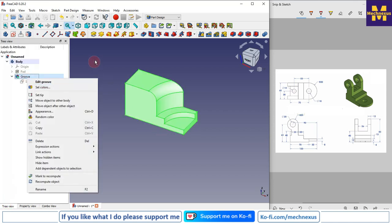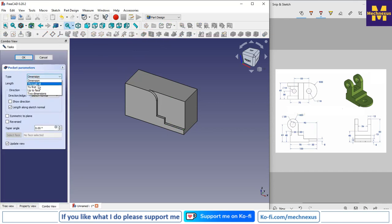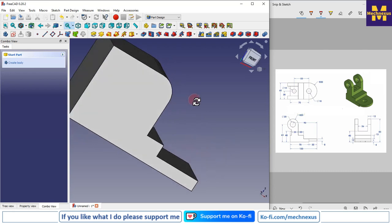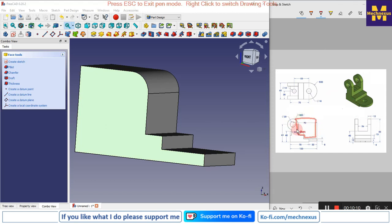So it took the glue command, so we will delete it, and we will go with a cut and simply say through all, right? Now we have removed the material at this location, and now our main target is to remove the unnecessary material whatever is left at this side, the left hand side.